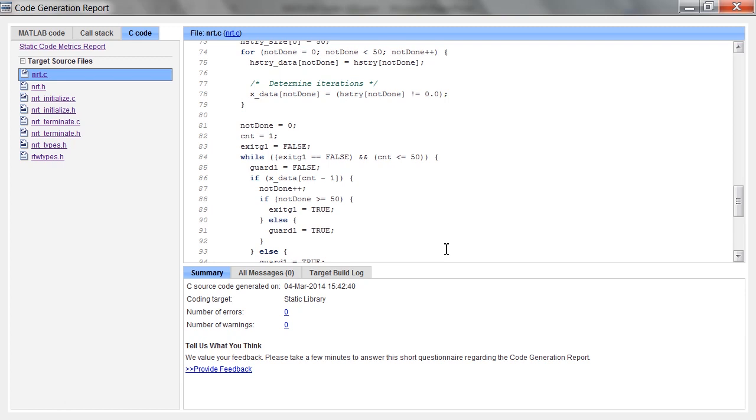MATLAB makes a large number of diverse functions easily accessible. Sometimes you run into code where a particular function is simply overkill for the problem, which leads to inefficient implementations in terms of performance and memory usage. In this case, we're doing something very simple. So let's see if we can rewrite that line of code and generate less C code. So coming back,